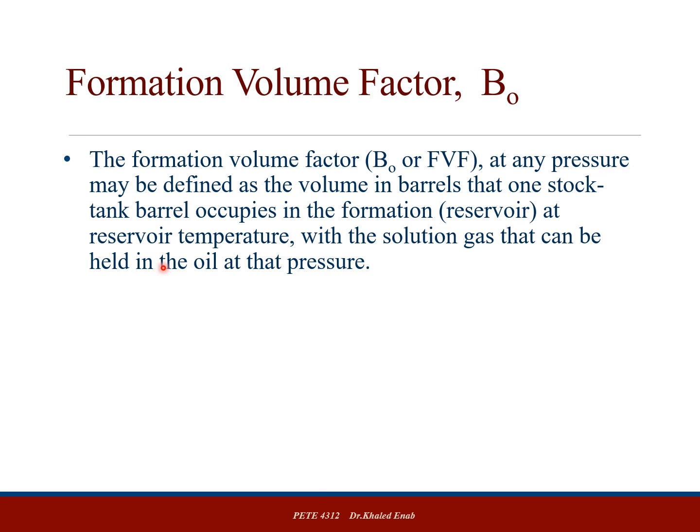It will always be more than one, because when you convert the condition from the surface to the reservoir, you are adding to it the dissolved gas. So formation volume factor equals the volume of the liquid under the reservoir condition divided by the volume of liquid at the surface condition. Okay.